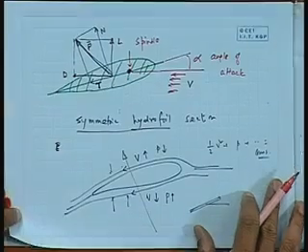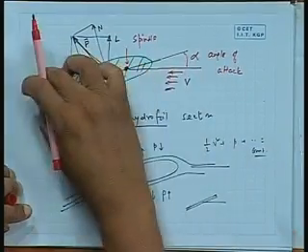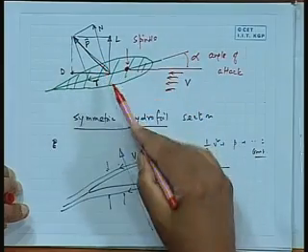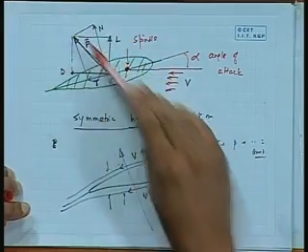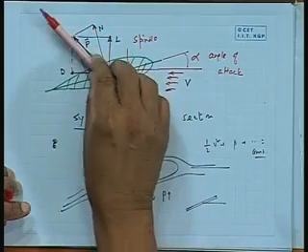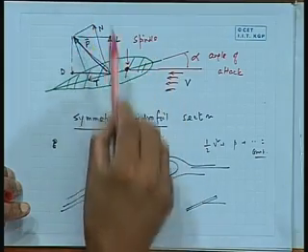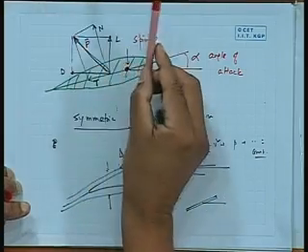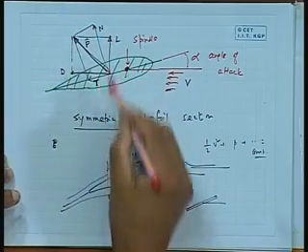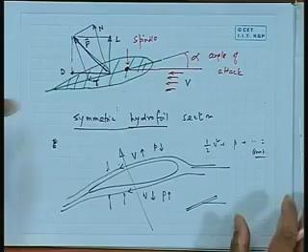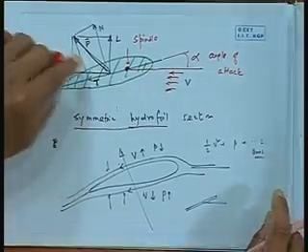Okay. So anyhow, this is a different theory, we are not going to talk about that so much. But coming back to this diagram, it will turn out that if you have a section here, and there is a flow there, it will always produce a force somewhat in this direction, and you want this direction to be more and more on this side, because you want more and more lift. You want much more L than T. But regardless of that, for all aerofoil theory, you get this.